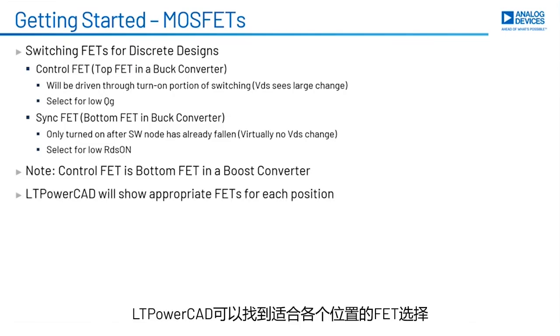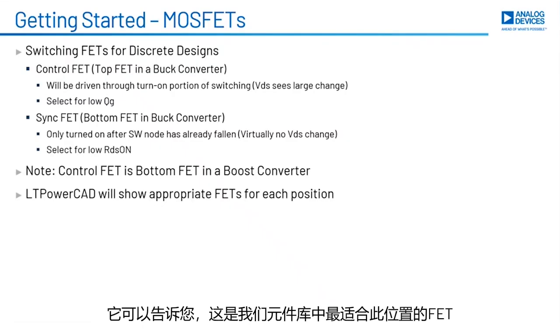LT PowerCAD will show you appropriate choices for the FETs in each of those positions. So that's another benefit to using that tool, because it'll tell you, here's the best FET that we have in our library for this position.